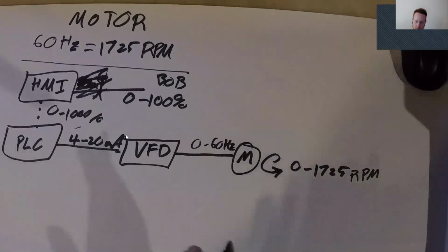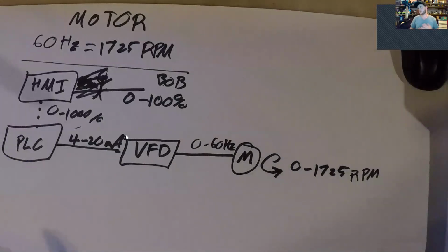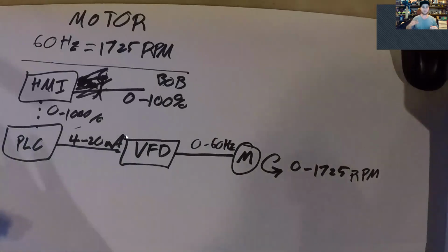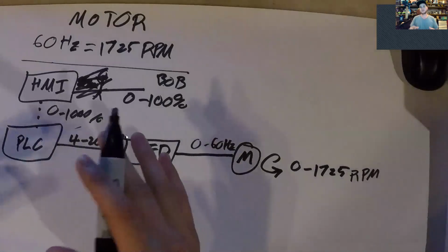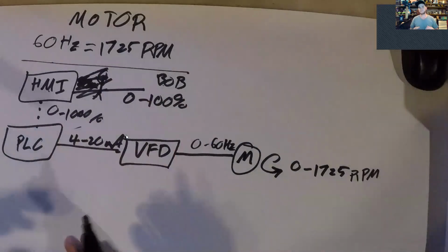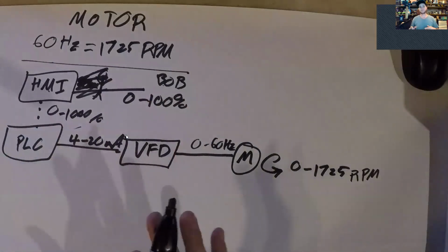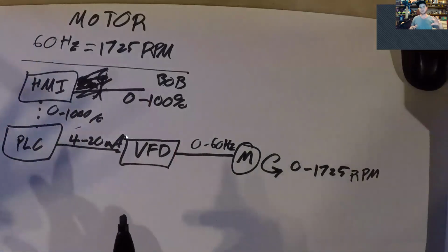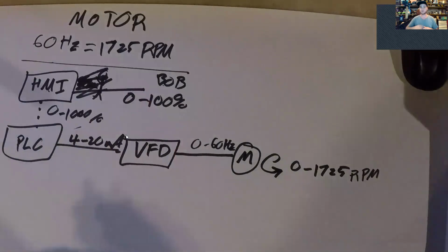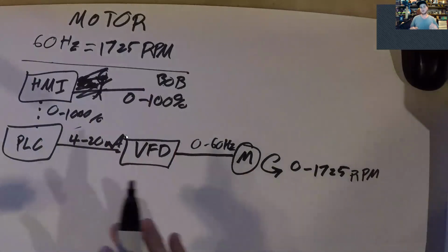You would expect it to drift a little bit, and that may be your actual process drifting, which is normal, or your instrument just has some inherent error bounds in it, and so the value you're reading on that instrument into your controller has some chatter in it. That's totally normal. We had to do some things in the ladder logic that I probably didn't go over in much detail to smooth that out and try to get rid of that fluctuation, but it's still going to be there.